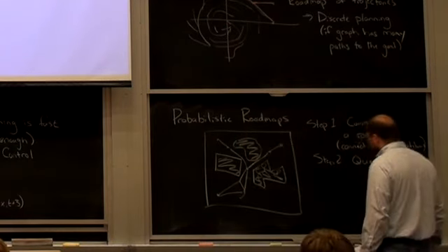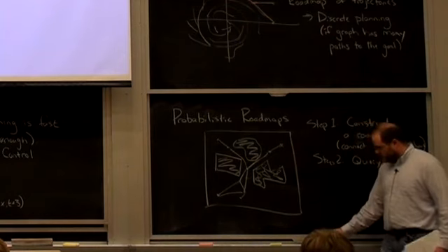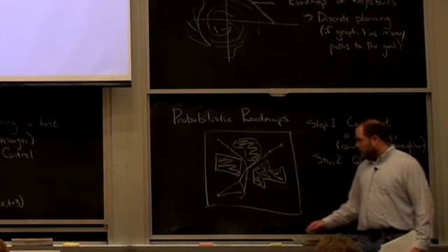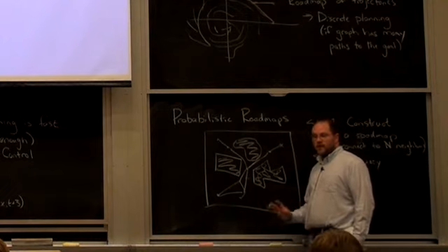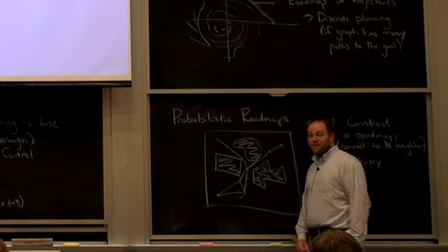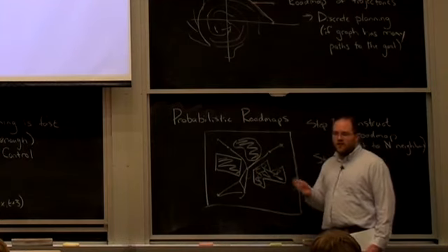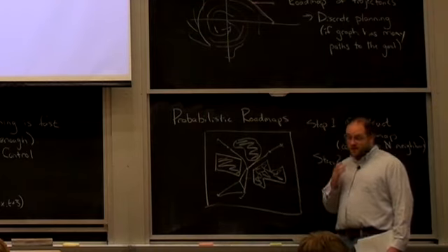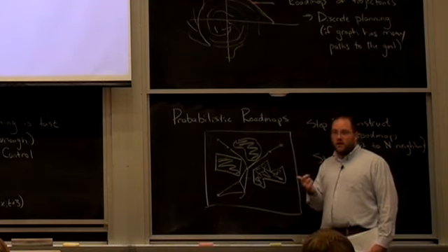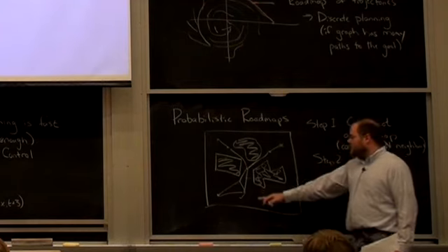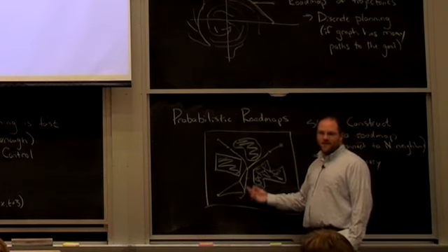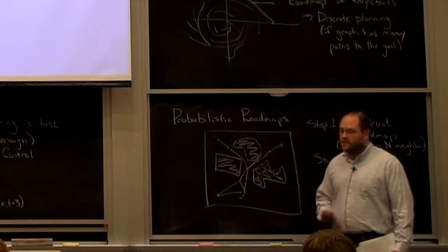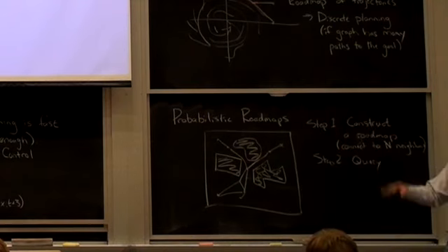Given a rich enough roadmap, would you have problems choosing the best path from among those paths? I mean, is it like discrete search? The discrete search, I think, in general, you should think of as being basically unlimited. Compared to all these continuous time methods, it's very, very efficient, right? People do it on huge collections of nodes very efficiently, especially if you can do sort of A-star if you find a good heuristic. This is how you go to, to maybe overplay the title, this is how you go to MapQuest and you ask it to go from Boston to California and it just happens, right? These things are very fast, even with a lot of nodes, a lot of roads.